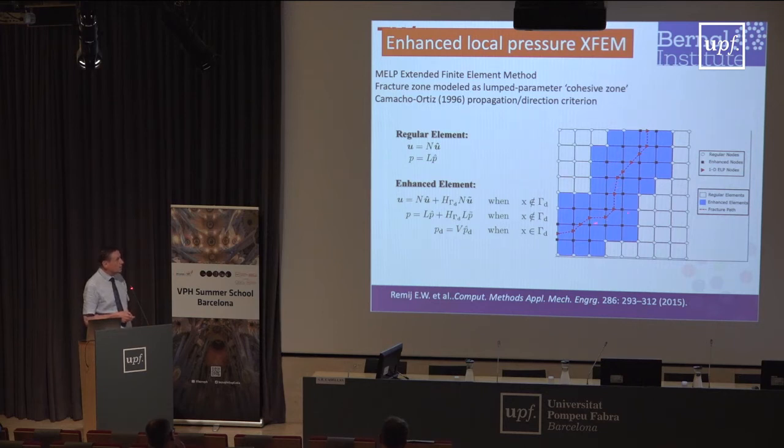What you basically do is use the same thing as regular finite elements, using displacement degrees of freedom and pressure degrees of freedom, but you enrich the displacement and you enrich the pressure by means of an extra discontinuous shape function. This is very standard stuff. Only what we did is, along the crack, we had pressure defined inside the crack, but also a pressure defined on the left side of the crack and on the right side of the crack.